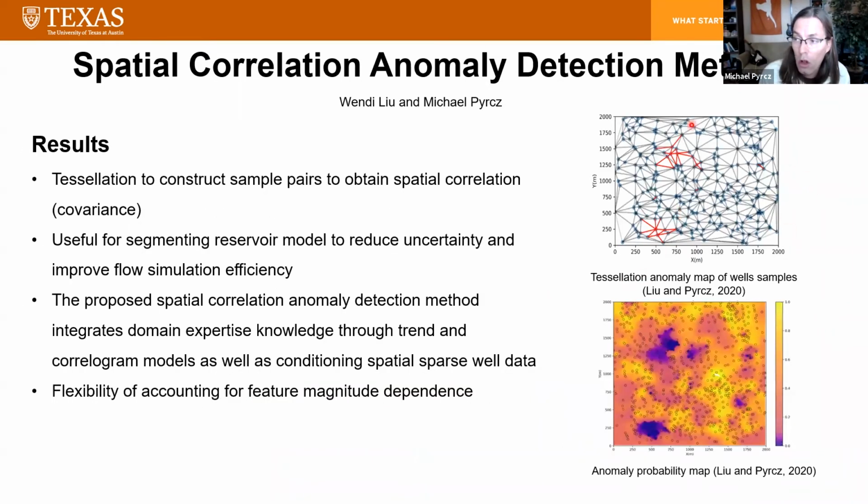So I can go through all of my spatial data pair by pair to the nearest neighbors, and I can identify a likelihood right here, going from very low likelihood of occurrence to high likelihood of occurrence. I can look through my spatial data and look at this data point right here. You see it's purple? That indicates that there's probably a blunder. There's a problem there with that spatial data. Right here, this entire region might be non-stationary. There might be a transition or change.